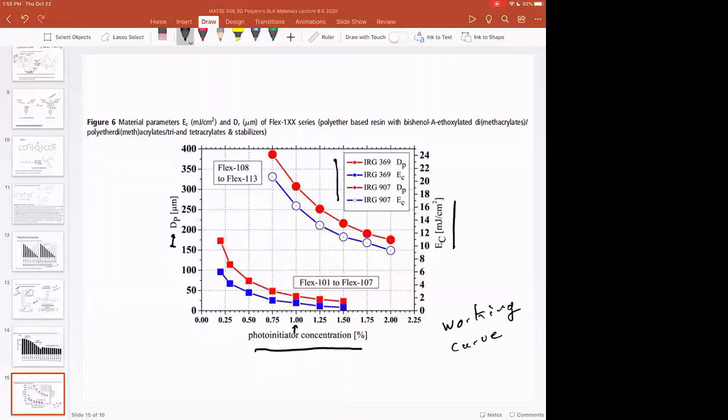They're specific to what photoinitiator you have, how much energy you can put in the system. And so these are often not universal, but they can be portable as long as you stick within some basic parameters. And most of the commercial resins out there use a very similar family of photoinitiators and similar families of laser wavelengths. So this still gives you a good idea for where you might want to be. Any questions so far?